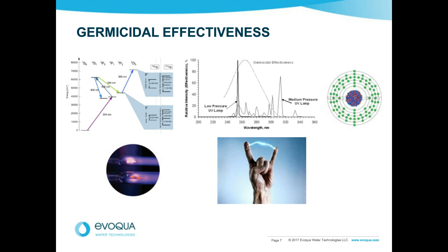I think it's the right application. Many membranes these days are very intolerant of chlorine, so you have to be very careful exposing a cellulose acetate membrane or the different membrane material to chlorine. So again, it has to be sized properly. You have to ask a lot of questions. You have to understand the pH of the water. You have to understand, are there chloramines present? Lots of questions to ask. But when you ask the right questions, funnily enough, it produces the right answers, and you can size it properly. So long as you understand what you're doing, it's a good application.